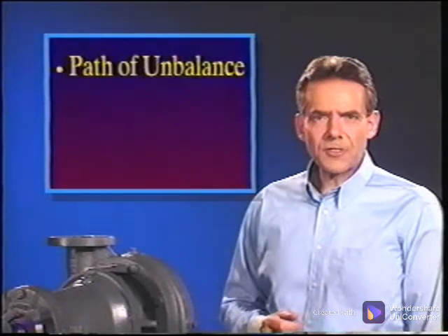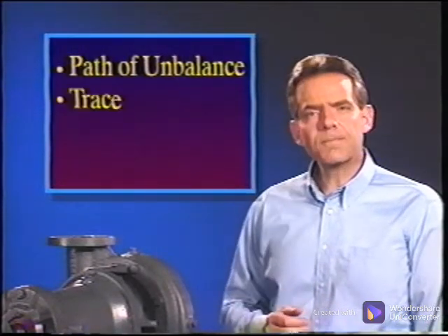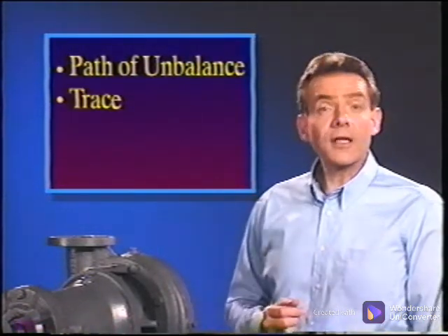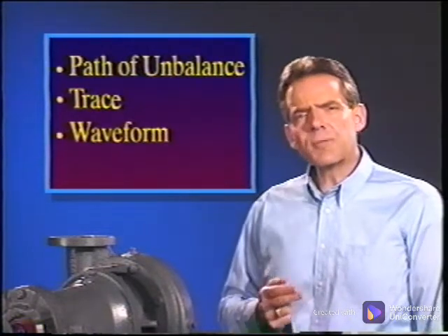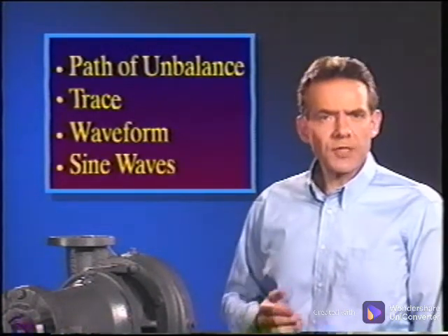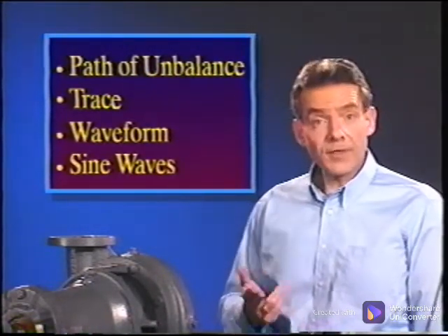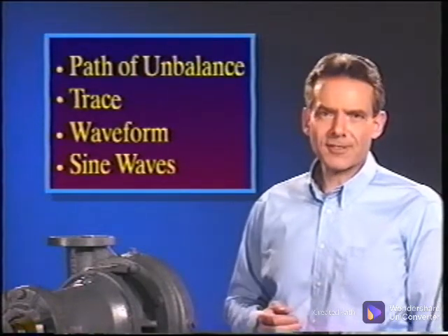Although we've been referring to this path of the unbalance as a trace, the technical term for it is a waveform. It is made up of the individual sine waves of the vibration of the machine, or in this case, the tire's unbalance. The analyst uses the waveform to indicate certain characteristics about a machine's condition. The analyst can view the same data from another perspective to gain additional information about the machine.